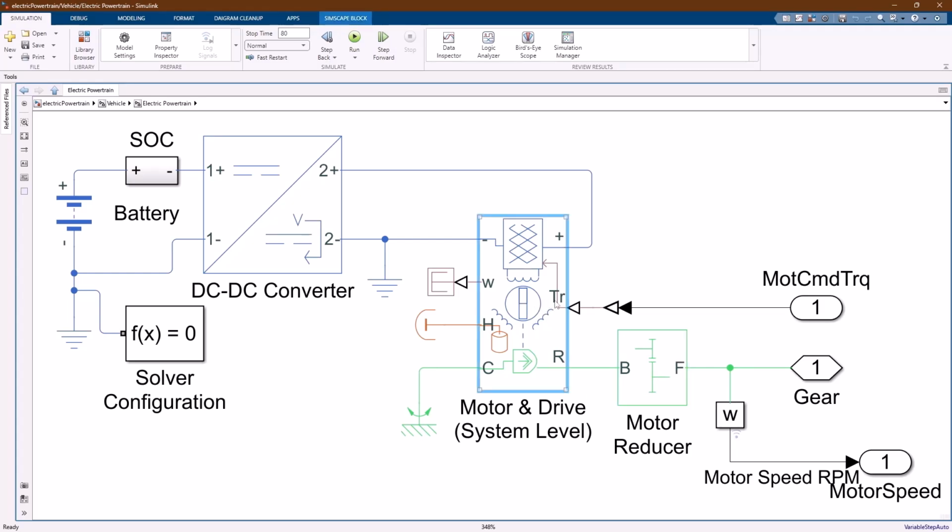The core of our powertrain here is this motor model. As you can see, it takes an input of positive and negative voltage. It takes a motor torque command in the form of a physical signal. And right now, although we model a heat output, we have it capped off with a perfect insulator because we don't have any model of how we're dissipating that heat.